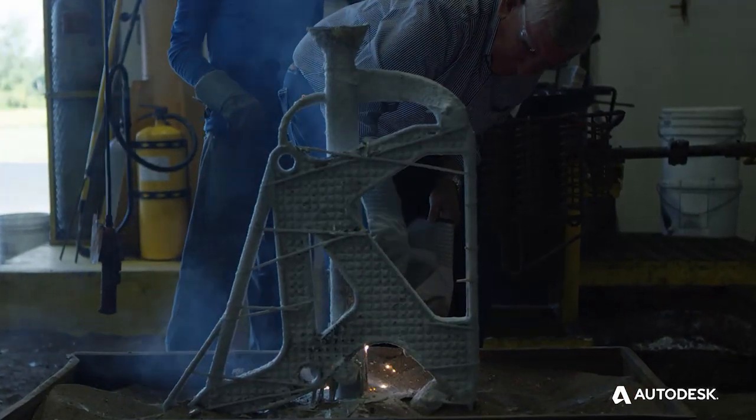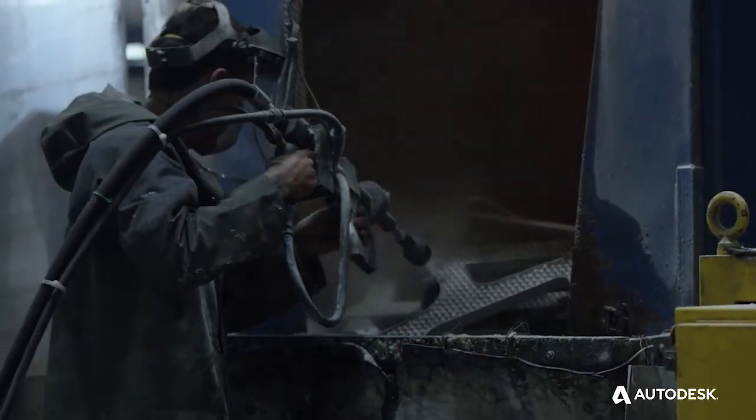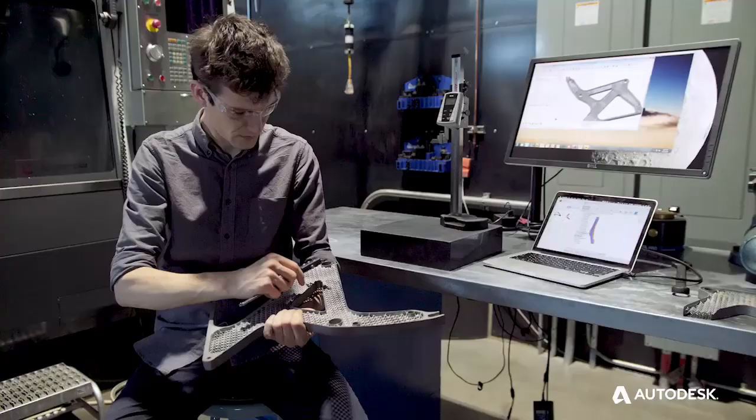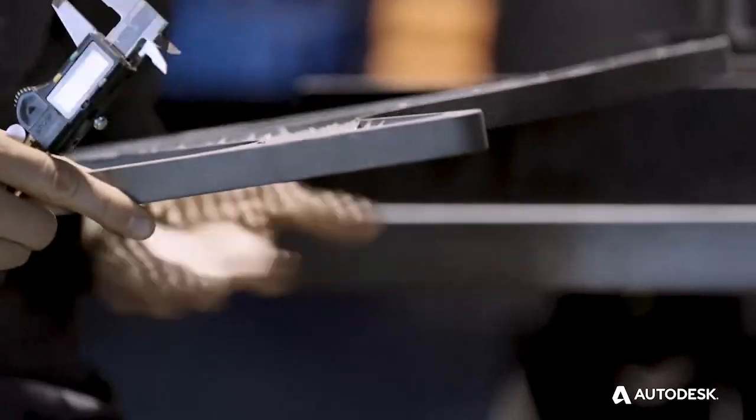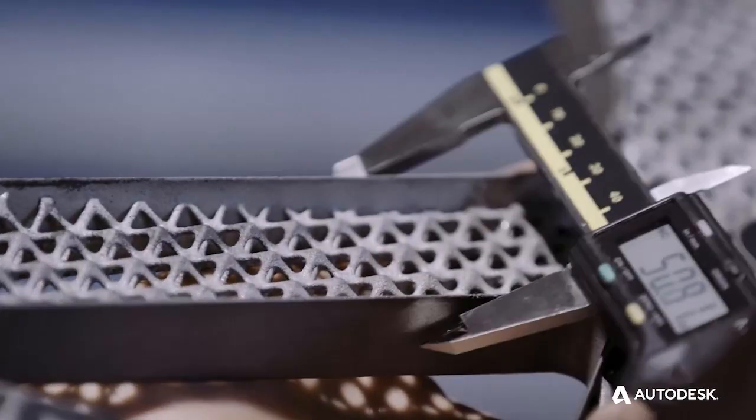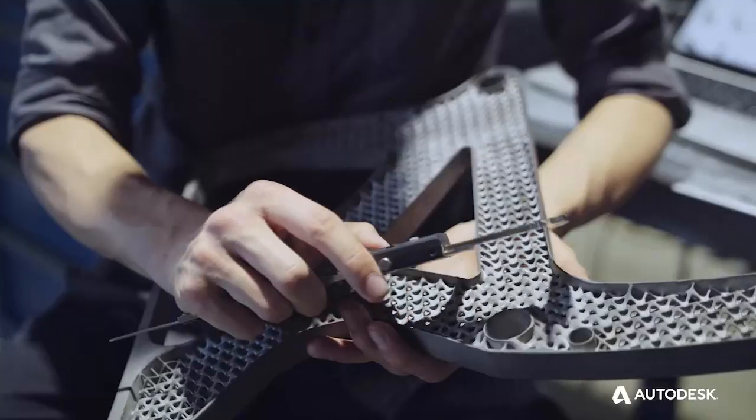From small startup operations to full production products, the ability to reduce weight while maintaining strength allows increased innovation and high product performance. There are, of course, downsides to additive when compared to subtractive. The materials that can be used are limited, it is much slower, and it is much less accurate. But that's where hybrid manufacturing comes into play. A currently used method leverages a full additive part that is inspected and then finished using subtractive manufacturing to bring critical surfaces to the required tolerance or surface finish.